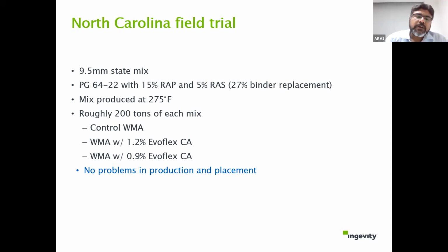In a hot mix, we have 7 to 8 passes to get your compaction. If you look at IRC, I think it's 119, or you follow the orange book, it says you need to achieve 92% of your maximum density. To achieve that, typically in India we adopt around 6 to 7 passes with 2 high vibratory rollers, a few normal rollers, and finally one pneumatic roller. When you go with RAP, this doesn't happen, and you may typically end up using more passes.